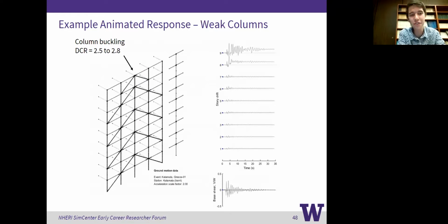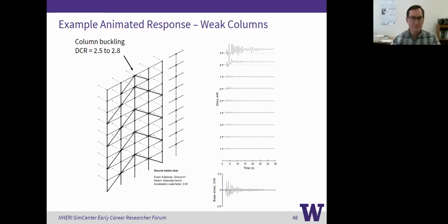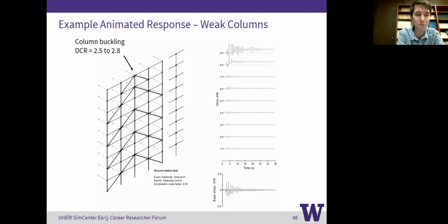You create a figure, and then using the deformed location of all of your nodes that you recorded in the analysis, all you need to do is change the locations of those nodes in each frame of the video. I think there's a get frame command and a write video command in MATLAB. And so it's all possible.